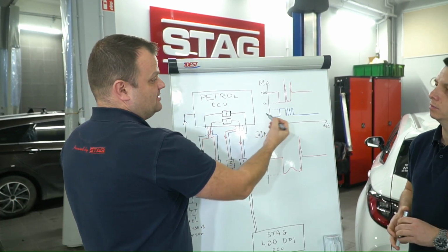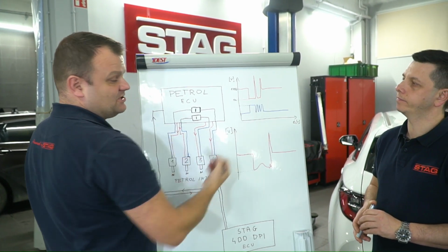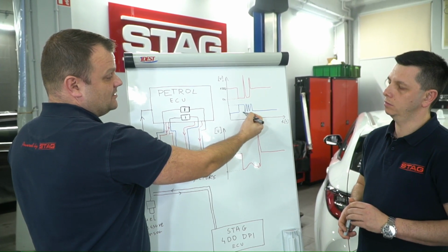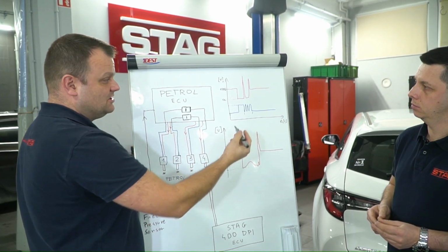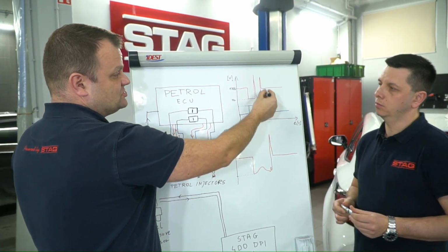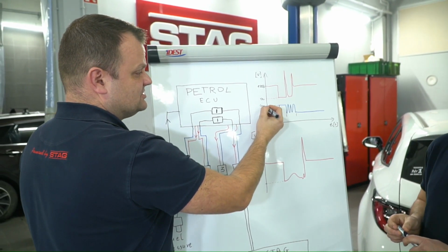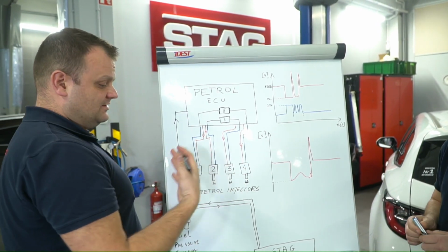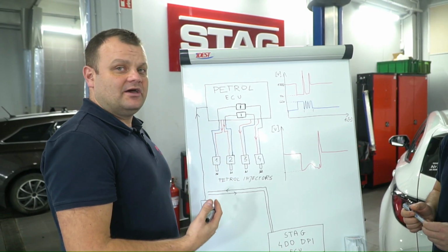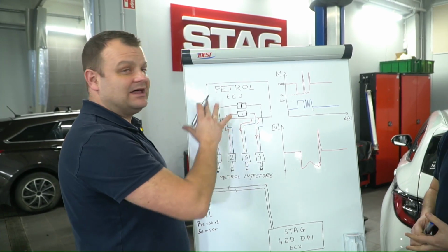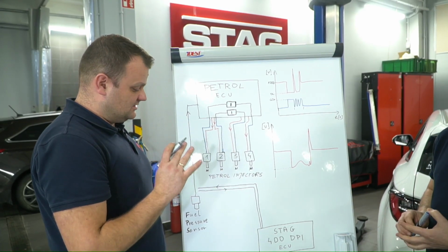But here, as you see, the red steering signal and the power supply signal is a PWM signal, so noises also occur, and this voltage can be also 60 volts. That's why the typical strategy of the MPI ECU is not ready to handle these signals. Yes, that's the main reason why we cannot connect it and use it.